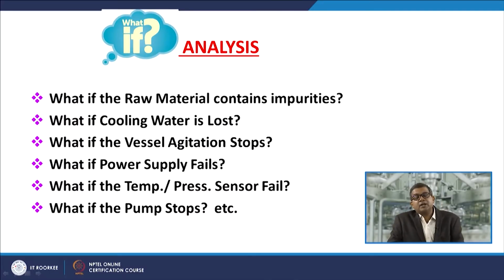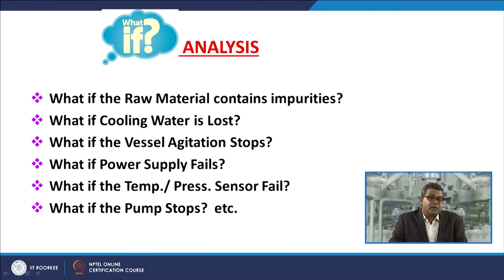Sometimes you are dealing with an exothermic reaction and you need to extract the excess amount of heat being liberated during the course of time. Then you need to pump in the cooling water or the cooling fluid for that particular system. So what if the cooling water is lost, or the supply of the cooling water or the cooling fluid fails?